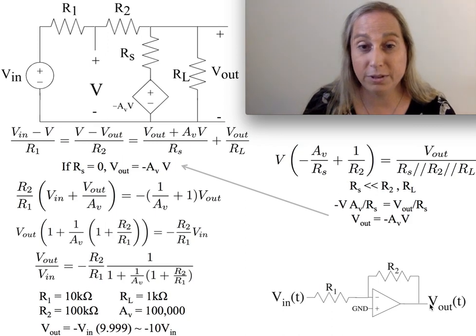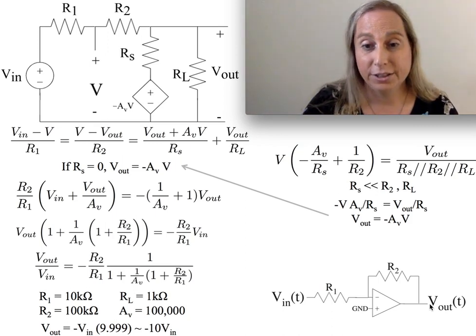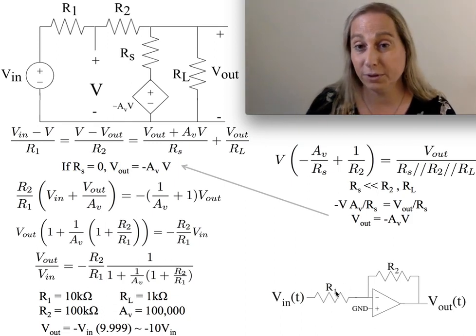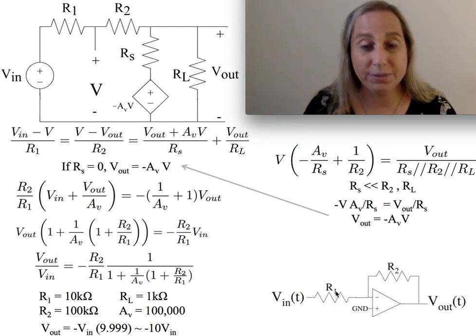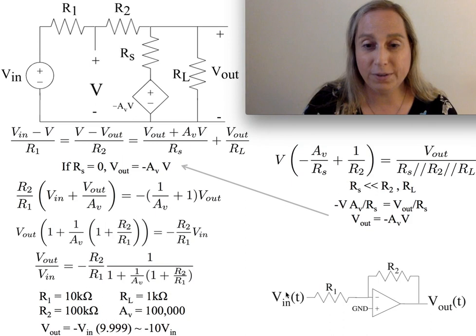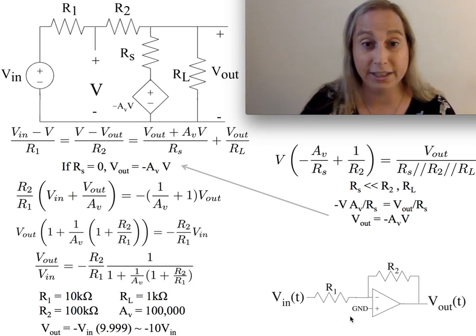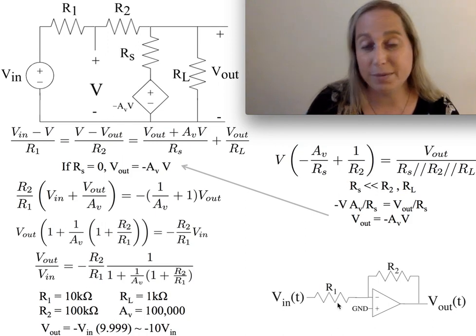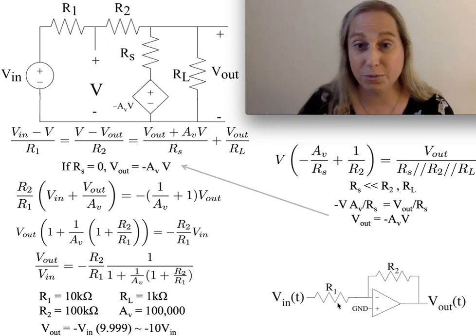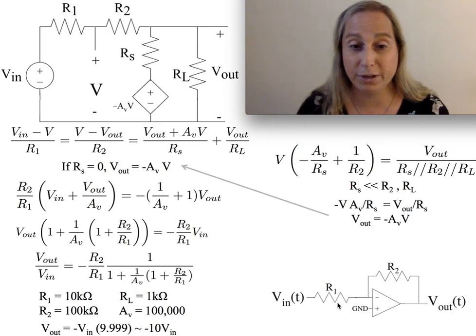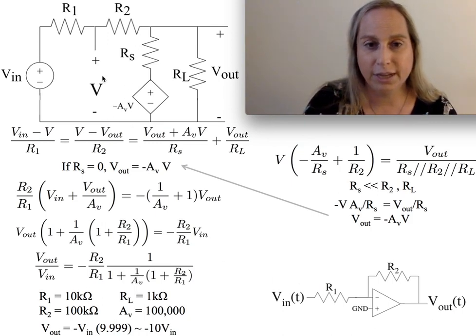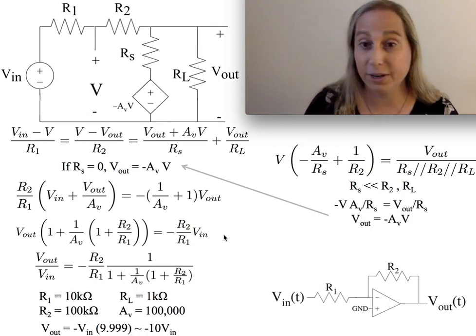When you analyze this circuit, you would expect a voltage gain of R2 over R1, and that it'll be inverting. These sort of things allow you to see where these analyses apply. Even more, if you get used to looking at this kind of circuit, there are some tricks to getting that answer very quickly. But if you ask what happens if my gain isn't super high, and what the correction terms would look like, well, I can always go back and reanalyze it in a very straightforward way.